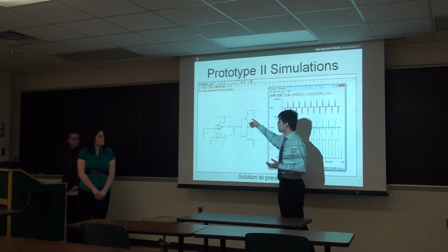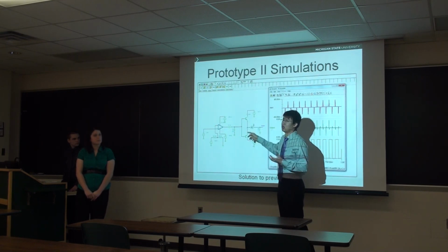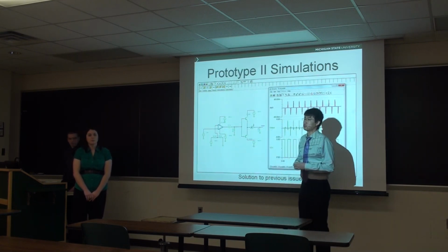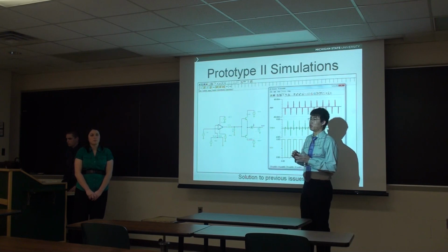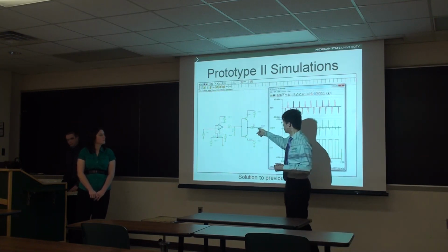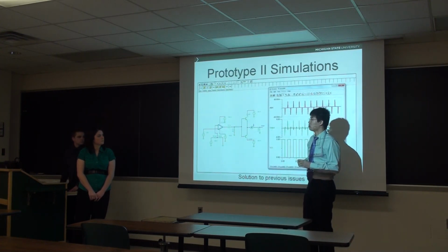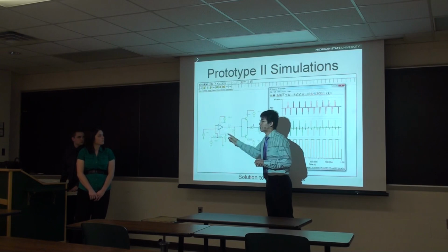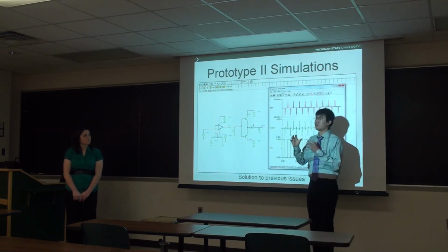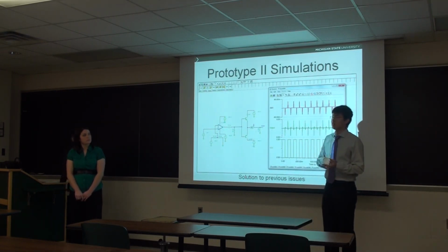And this push-pull circuit is basically a current amplifier, so the voltage waveform ratio is 1:1. So we're going to give a higher current to the solenoid. So that's why I use the op-amps to convert the signal to -5 to 5.